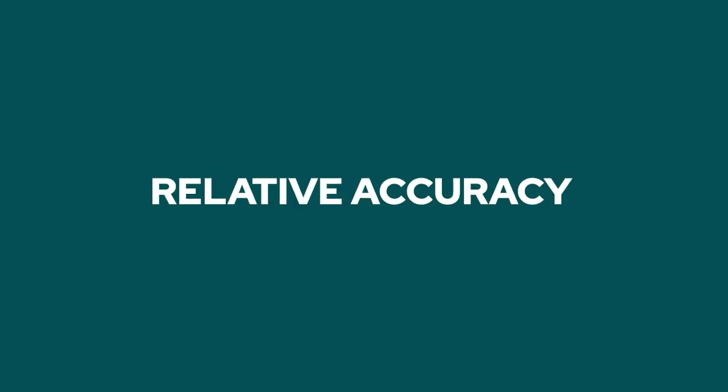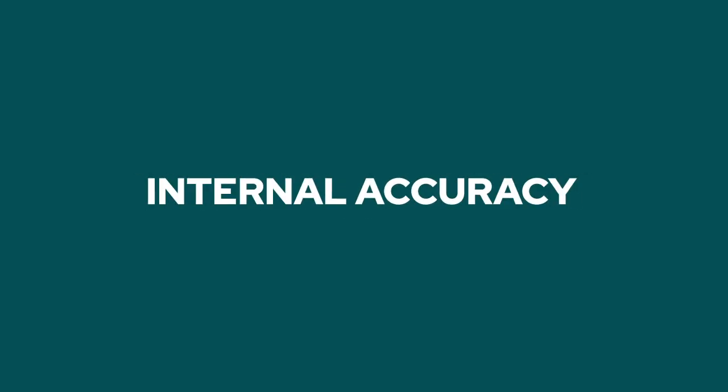Okay, so what we're going to do today is actually we're going to start with something called relative accuracy or internal accuracy. Now, the big use case for relative accuracy or internal accuracy is actually measurements. So if you want your measurements to be accurate, one of the things you've got to pay attention to is how good is your 2D map or 3D model that you've generated from the drone data.